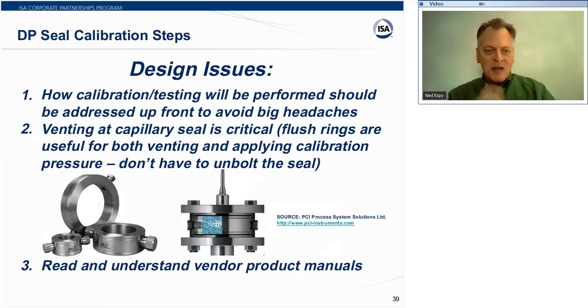Let's see if we can talk a little bit about the logistics of installation and being test ready. Hunter went over a lot of good details on application and what's the best thing to use. Also, I highly recommend you consider how you're going to test these transmitters. As Hunter said, they're fragile. You've got these capillary tubes flopping around, so it's really good if you can design up front how you're going to test these types of transmitters.